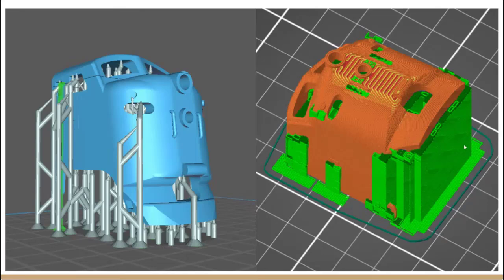If something breaks easier than you expected, or you're in here sanding and you snap something and didn't realize it, go back into your slicer program, orient your model in such a way that the thing that broke won't break, by making sure that that feature is printed with long strands rather than layer by layer.